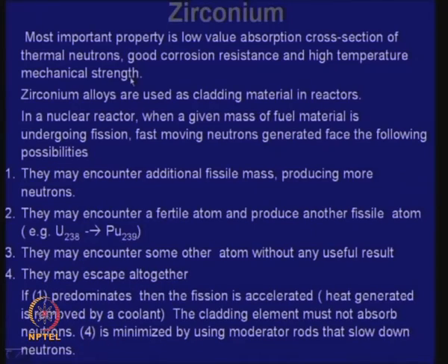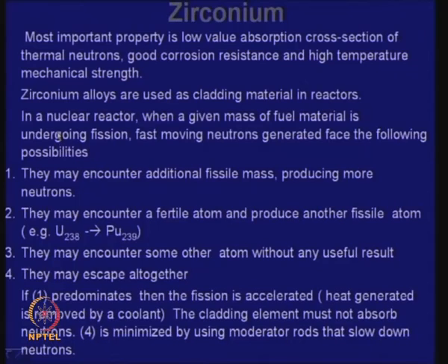So, all these make it an ideal material, of course not pure zirconium, some other things are mixed with it to form an alloy which will stand high temperatures, which will not be corroded, which will stand all the radiations in the nuclear reactors, and most important, it will not absorb the neutrons, because it will allow the neutrons to pass from one pile to another pile to carry on the fission reaction.